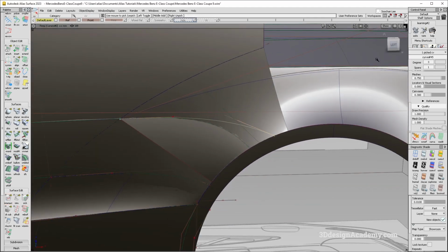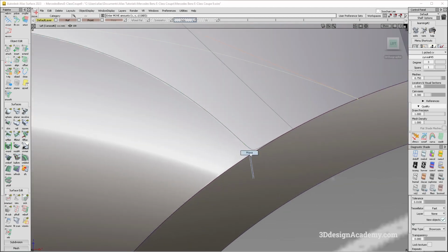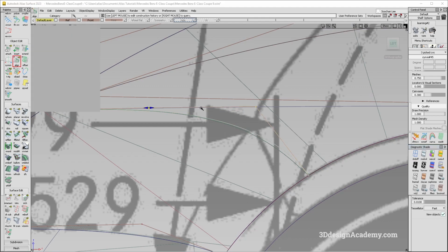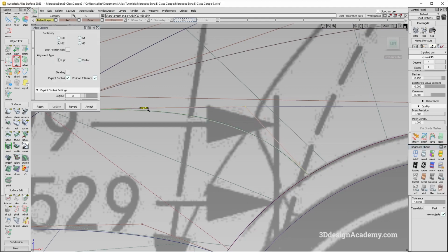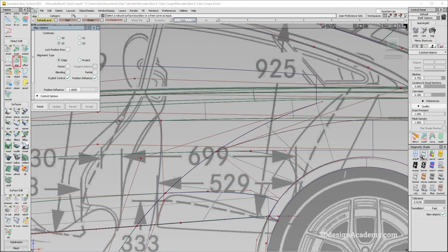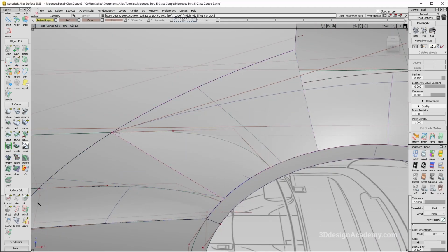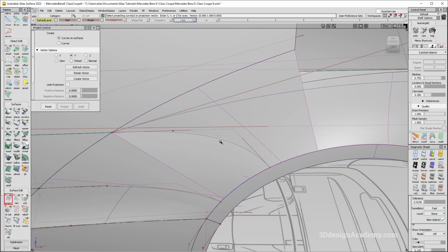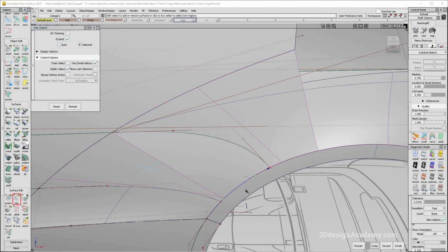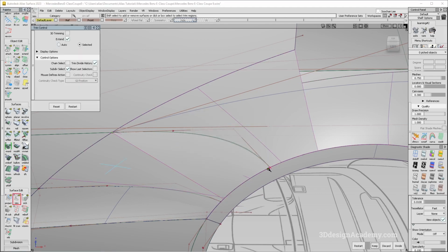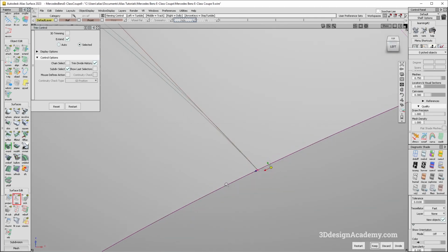I think I'm actually going to snap a curve right here to just cut those out. So let me just make it a little bit similar in section between these two. Now I'm just roughly cutting it so that it's easier to see. This is not going to be the final intersection that's going to be used. So let's go ahead and pick these two surfaces, project with the curve. I'm going to trim over here. These I'm going to get rid of. Trim over here. Why is it saying that short?